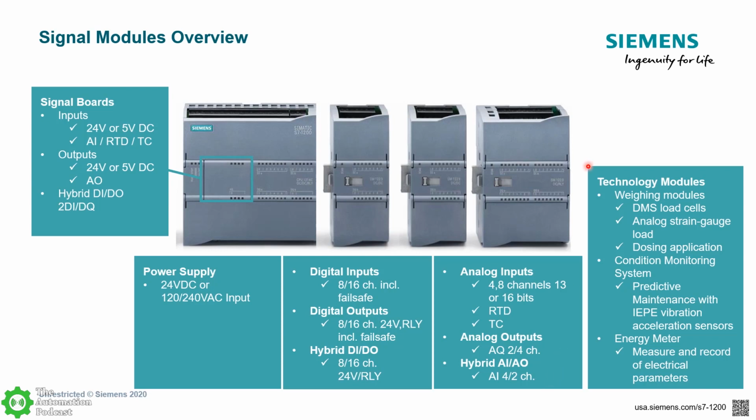we always kind of get people scratching their head or asking about what is a technology module. We always hear about that. Well, technology modules are basically specialized I/O cards that handle special functions. So we have signal modules that can handle weighing applications. So like if you have strain gauge or load cells or dosing applications, we have weighing cards that you can stack to the right of the CPU that can handle that kind of